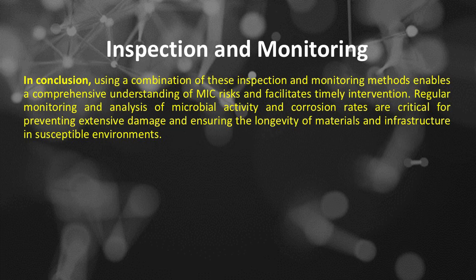In conclusion, using a combination of these inspection and monitoring methods enables a comprehensive understanding of MIC risks and facilitates timely intervention. Regular monitoring and analysis of microbial activity and corrosion rates are critical for preventing extensive damage and ensuring the longevity of materials and